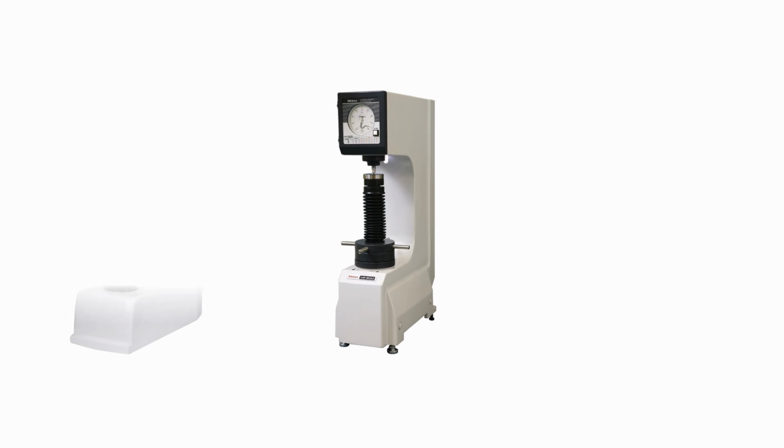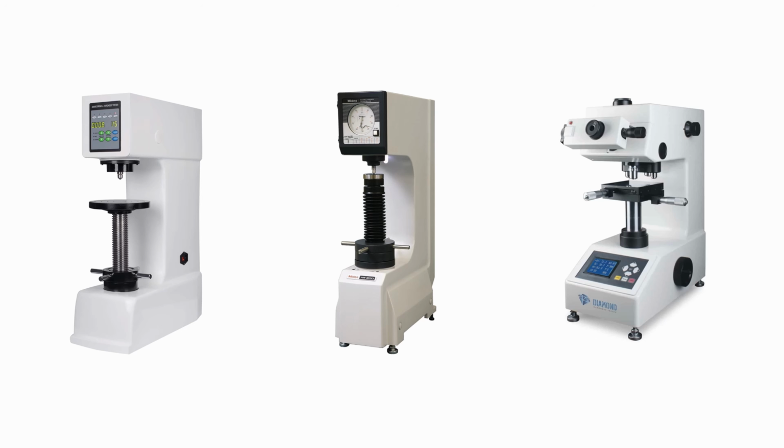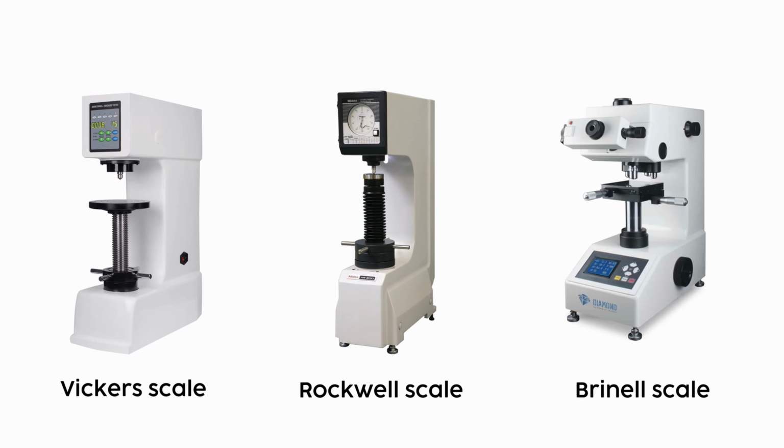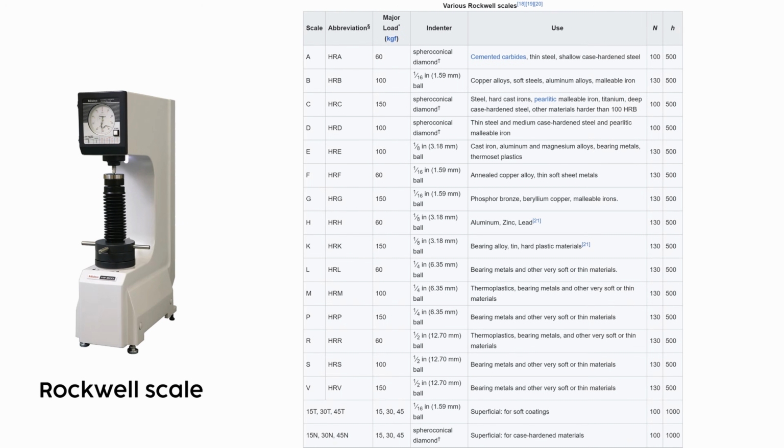And there are various testing machines for macro indentation hardness testing, and they measure the hardness on different scales such as Rockwell, Vickers, and Brinell scale. Now, before we dive into each hardness scale, let me clarify, in case you are wondering, why there are so many scales instead of just one. Because later on you will notice that within some scales, like the Rockwell hardness scale, there are also some different subscales like HRA, HRB, HRC, and so on.